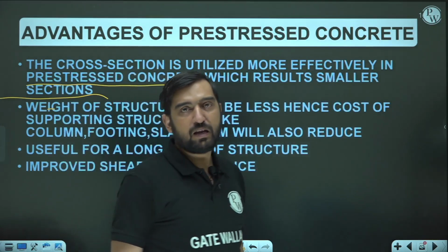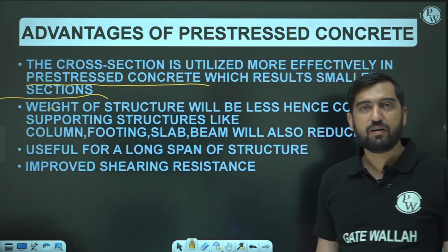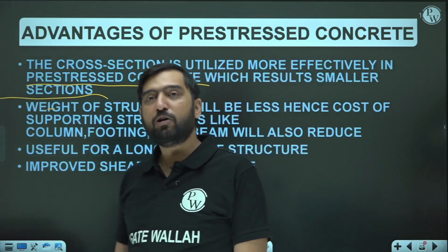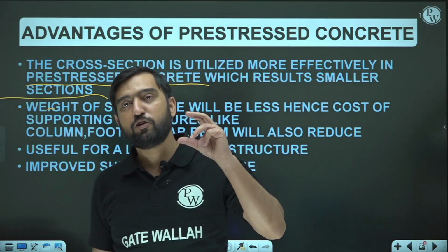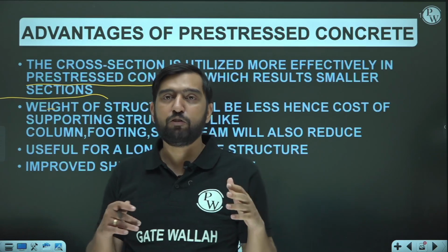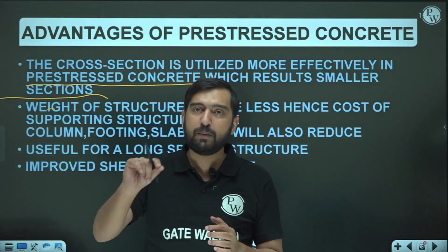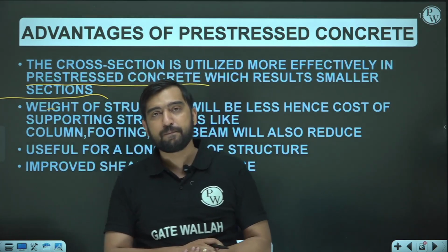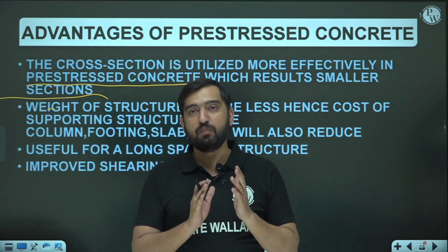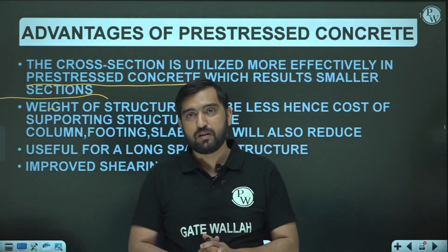Yes, so I was telling you the weight of the supporting structure will also be less, like column, footing, slab, beam, they will also be reduced. I am not saying that the original cost of pre-stress concrete will also be less than the RCC. It's not like if we are using a lesser amount of concrete, you need to pay less. Obviously, for the concrete portion you are going to pay less, but pre-stress concrete requires more skilled labor as compared to our conventional RCC construction.